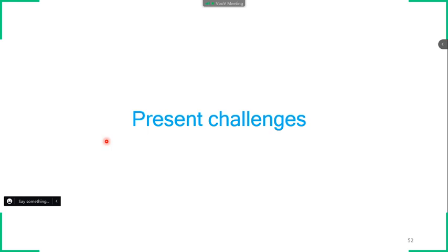Then for subsequent layers, you have to minimize the dilution, or else it will consume a lot of material. But for the first layer, the dilution should be good so that it can properly anchor with the substrate. Understood, no?